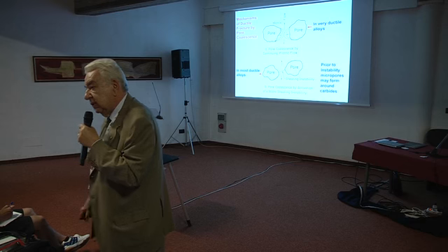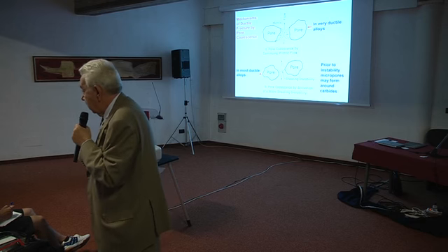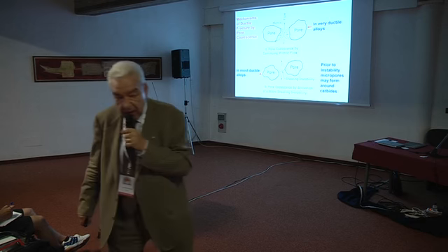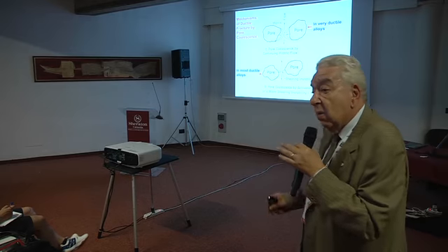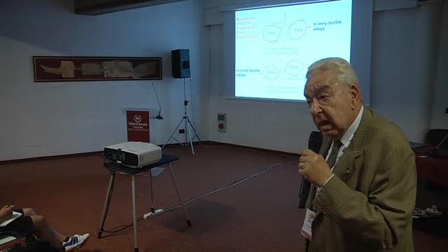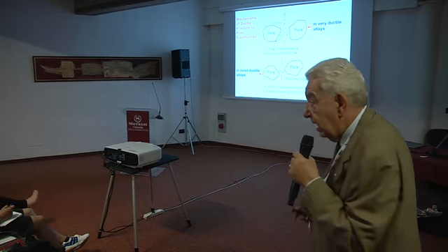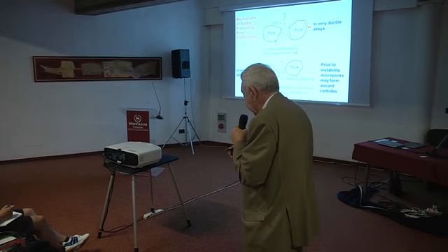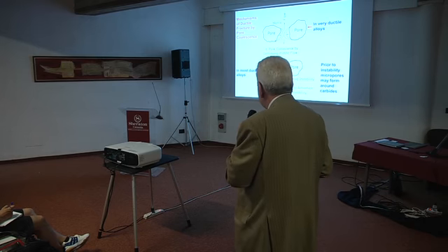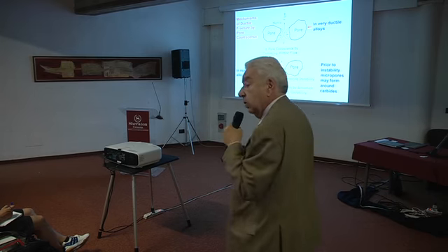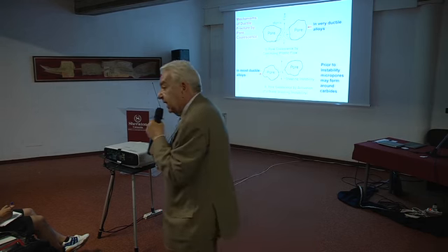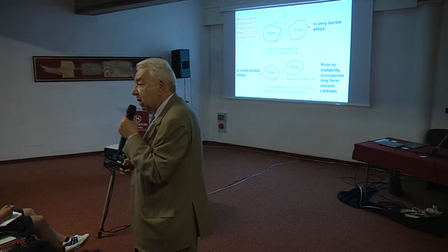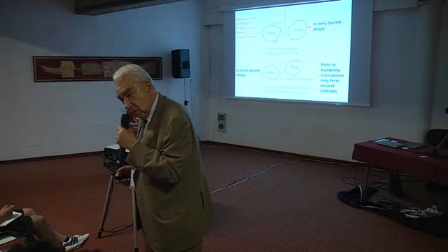Let us suppose that you have copper, oxygen-free, high conductivity copper, which is one of the most ductile materials ever. What do you have? You have a ligament between the two pores, and you stress the ligament with a stress that causes plastic flow.